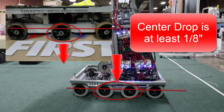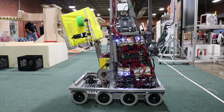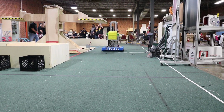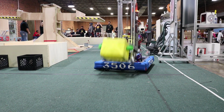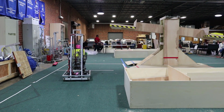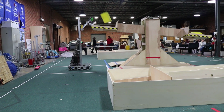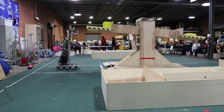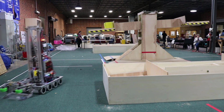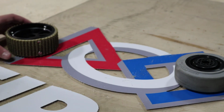If you have pneumatic wheels, you can adjust the drop to a larger number like 3/16, 1/4 of an inch, or even 5/16. But if you drop too far, your robot is going to tilt back and forth on the front and back wheels while the other set in the middle is on the ground, and this is going to make the robot harder to drive because it's going to wobble, especially on taller robots. This is one of those things that it does not hurt to do a little more research on Chief Delphi. You can read up on some of those drop center threads, but we have used mostly traction wheels or Coulsons, and so far 1/8 of an inch has worked for us every year on 6-inch and 4-inch wheels of different types.